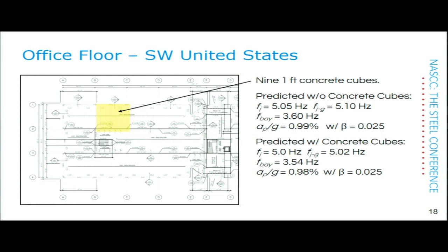Assuming a damping ratio, beta there is damping, of 2.5%. The way you get that is 1% for ceiling and ductwork, which was below, 1% for the structural system, and then 0.5% or 1% for the fit out, depending on whether it's what's called an electronic office or a paper office. An engineering office being a paper office, with paper and stuff all over the place. Electronic office, one where there's just consoles and computer screens.